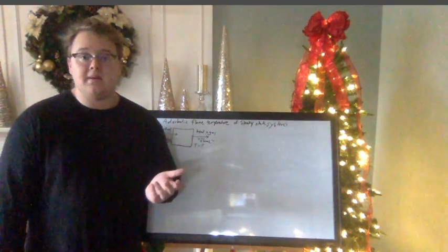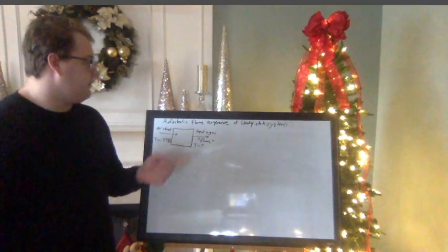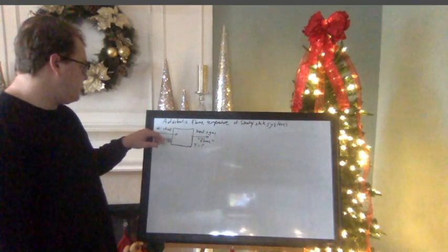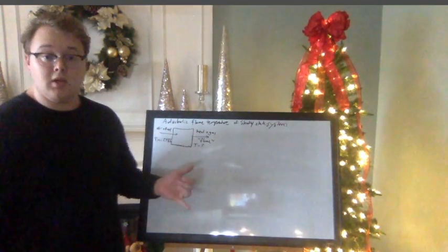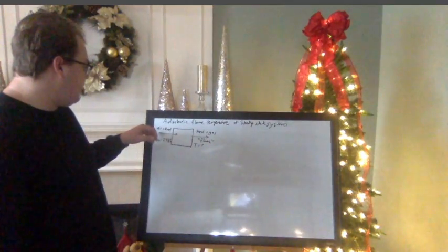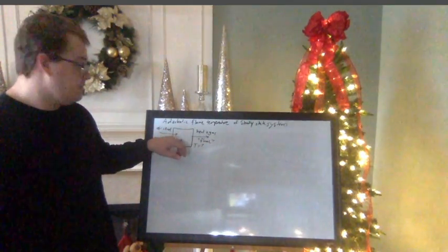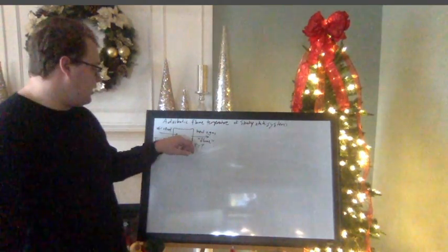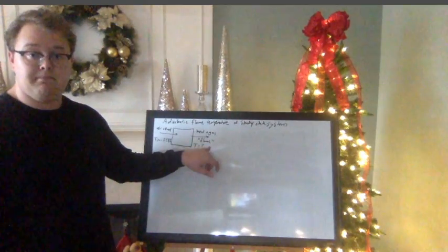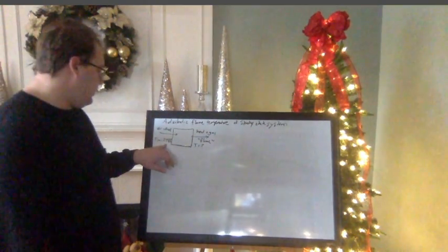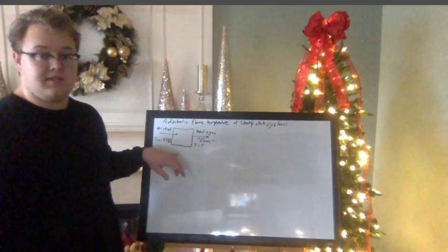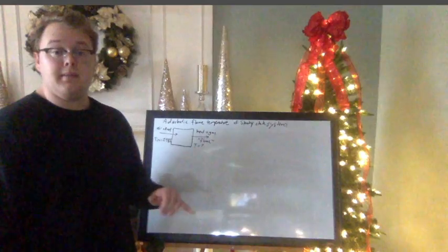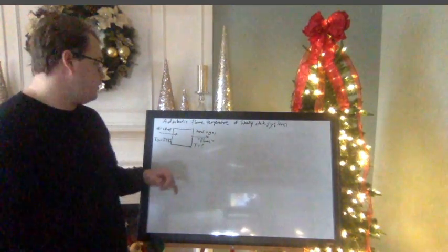And that brings me to the topic of this video, the adiabatic flame temperature of a steady state system. So let's say we have some sort of system, it could be our blowtorch that we're using, and we have air and fuel coming into the system, and we have an extremely high temperature gas exiting the system as our effluent. So we're going to call this our flame. Let's assume that the temperature coming in to our system is 298 degrees Kelvin, and we're trying to understand the temperature of our flame that's going to be coming out of the system or out of our blowtorch.